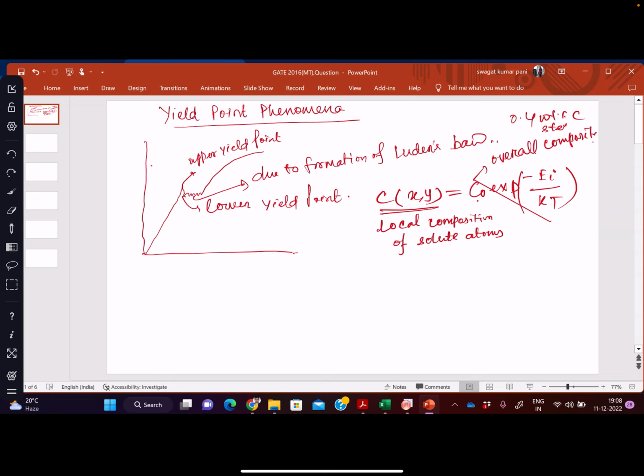Okay, so this is called interaction energy. Sir, what is X and Y? That depends on the location of the atoms; this comes from dislocation theory. The interaction also contains an XY component, depending on what position you are looking at. Dislocations have stress fields. At specific X and Y positions, there are specific forces on dislocations.